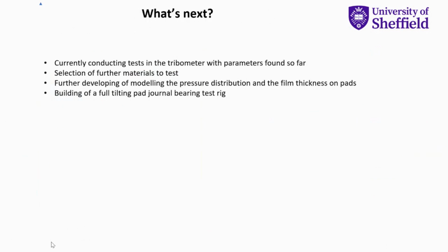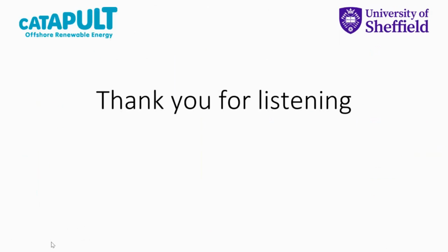I want to further develop my model of the pressure distribution and the film thickness on pads to better inform my test matrix. And finally, I'm building a full tilting pad journal bearing test rig, and that test rig will have tilting pads which will be lined with PEEK, and I'll also have some ultrasound sensors in there to measure film thickness, and that will give me a much fuller picture as well. But yeah, that's everything. Thank you for listening.